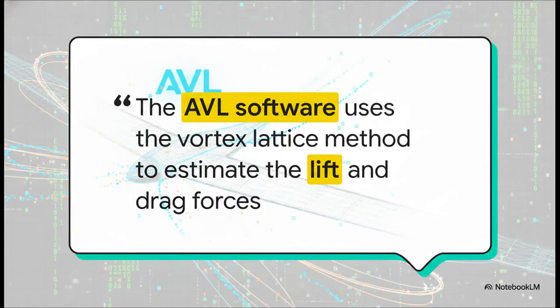So why these specific numbers? Well, they were carefully calculated and verified by advanced computational fluid dynamics analysis, specifically using a program called AVL. Engineers chose these exact parameters because the Odyssey isn't just up there flying around for fun, it has a very specific job. It has to carry a highly critical 14-pound payload. The Vortex lattice method inside that software ensured that every single value we're looking at optimizes lift specifically around carrying that heavy payload. To do that, we have to start with the environment.